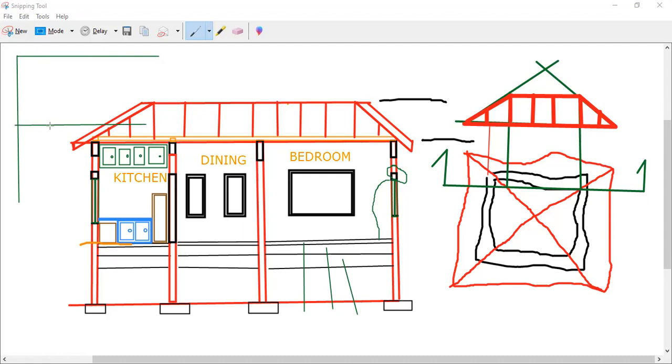You would then start from the finished floor and offset downward to get the first layer. You could do it this way, or you could draw the walls first and then offset. It's totally up to you. I typically draw the walls first. So this is my first wall, the outer left wall.